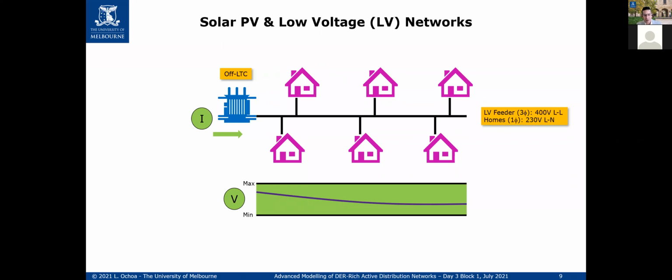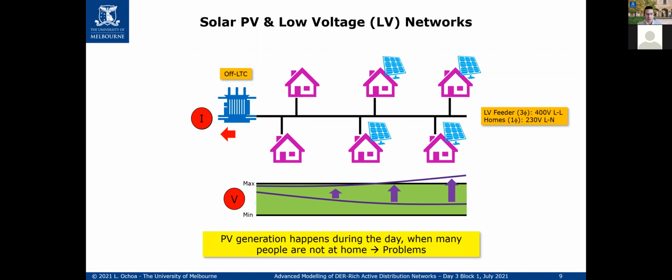Everything is done. So you have assets that are not congested, and you have voltages that are always within the statutory limits. That's how we do it everywhere in the world, with different ADMD values, of course. The challenge is that you design that low voltage network, and then suddenly people are having photovoltaics. The thing with photovoltaics is that the sun shines to everyone simultaneously. And then that means that when no one is at home, all these photovoltaic panels can create reverse power flows, because of course, your fridge might be using electricity, but it's super tiny and it's cyclic anyways.